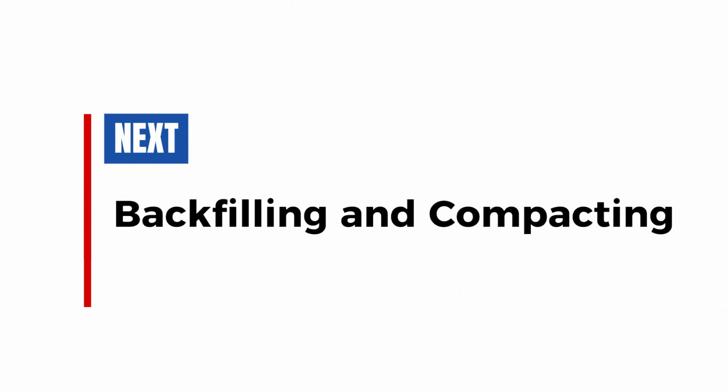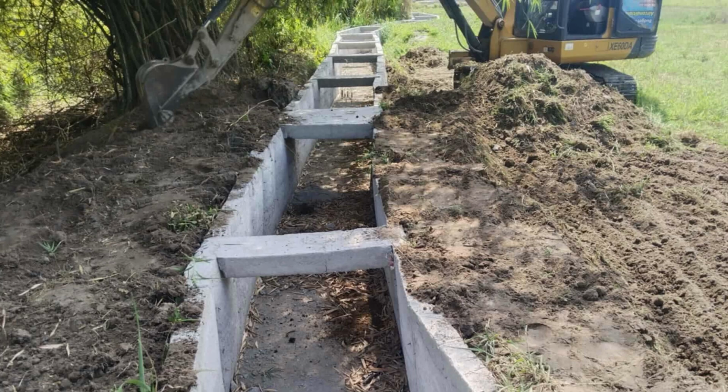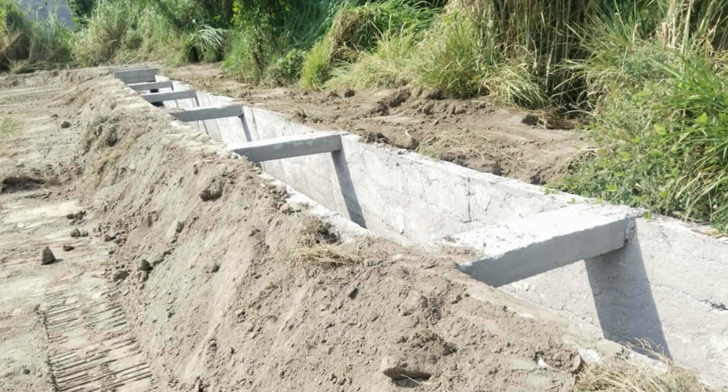Backfilling and compacting. Backfilling and compaction must be carried out properly to ensure that the required degree of compaction is achieved. This process is essential for providing adequate soil stability and support for the structure, preventing future settlement or deformation.